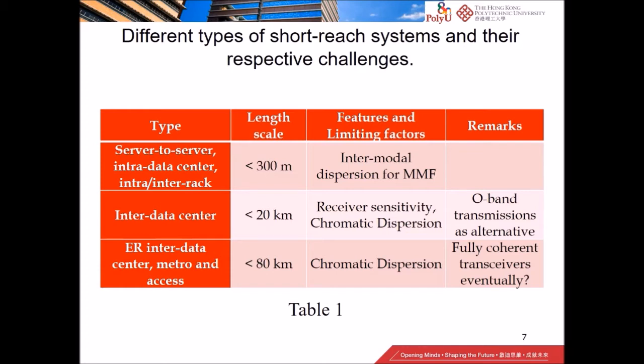Even though the effect of CD is linear, we are talking mostly about direct detection systems, and so the effect of CD, after direct detection, is not a simple impairment that can be easily mitigated by DSP. Also, if people have a choice, you will still want to minimize the amount of signal processing. So that's why CD can be an issue for these systems.